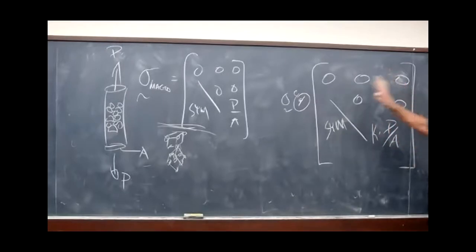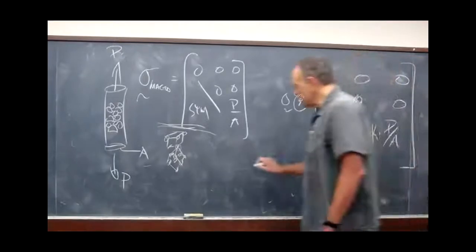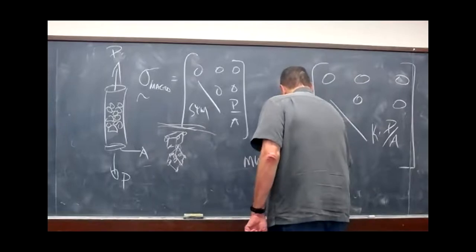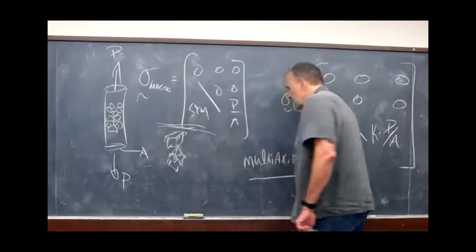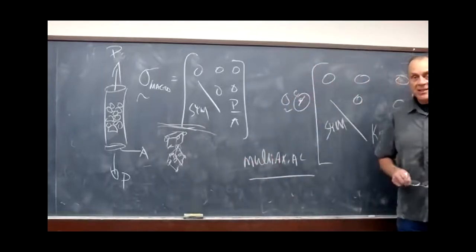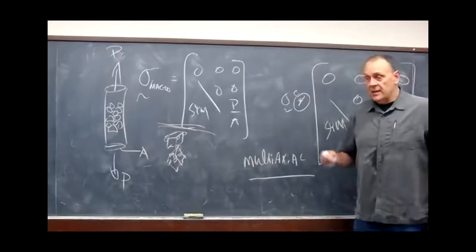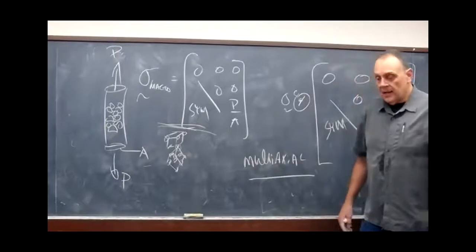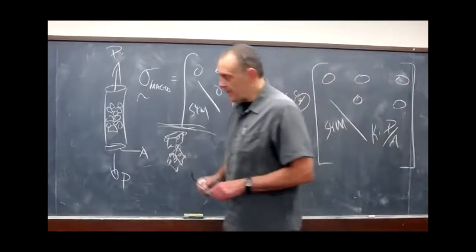We get full stress tensors at the crystal scale. Now, certainly, if it's loaded in tension, it will bias this, but it's a fully multi-axial stress state. And for those of us interested in plasticity or fracture or anything else, knowing that the stress is not just uniaxial anymore kind of changes your life.